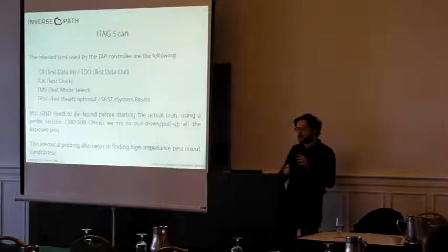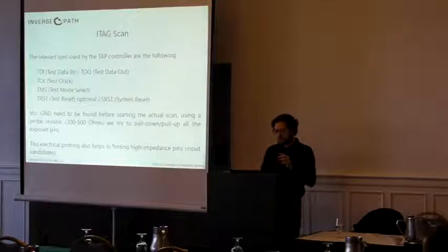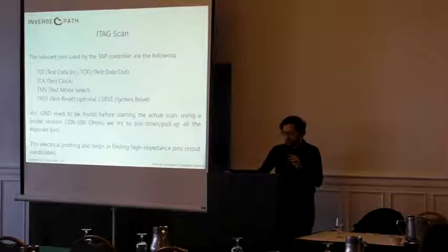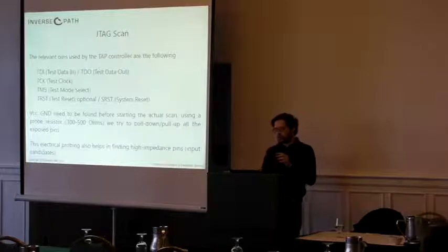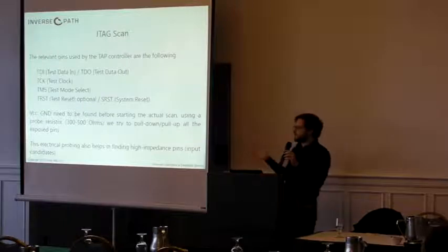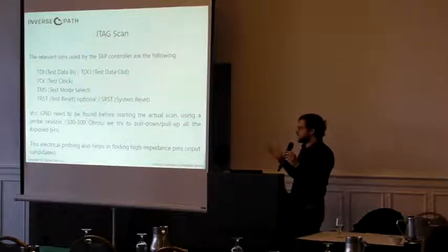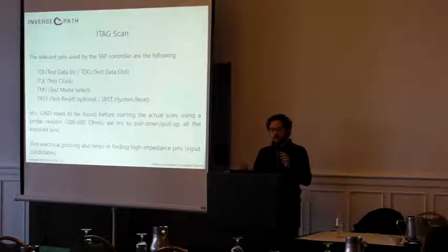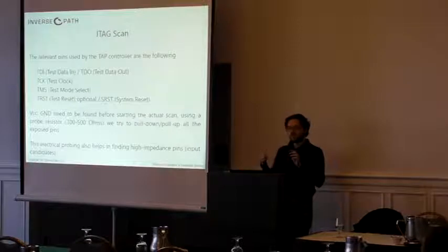And this is, of course, not documented if you're dealing with some remote avionic system which you know nothing about and you need to exploit. And this is one problem. But usually you can work around it, and by probing very carefully, you can understand where the actual pins are. So, for instance, ground and VCC, the voltages are really easy to find because you can try to pull them down and pull them up, and if something will not pull down, then that's VCC, and if your connection will not pull up, then it's going to be the ground connection.